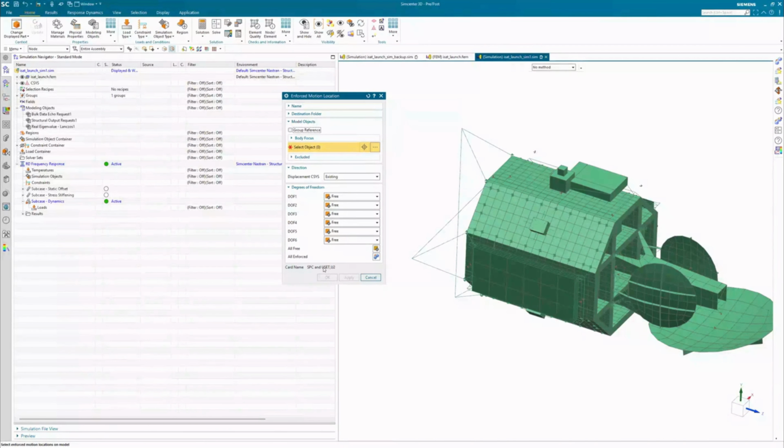This will tell Nastran to generate constraint modes for each of the directions along which we want to apply forcing. So we're going to start by selecting the node where we want to apply our enforced motion, and then we're going to select all three translational degrees of freedom at that node. So that's going to create a constraint and a constraint mode for those 3 degrees of freedom.